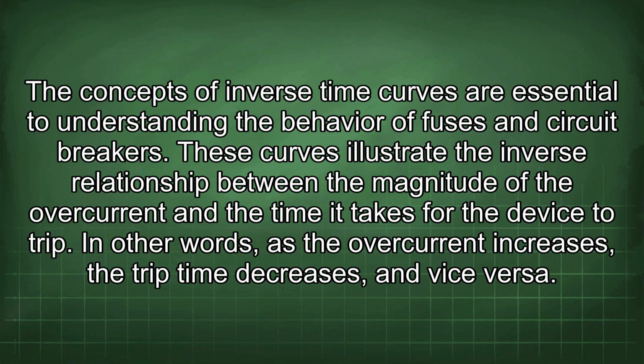The concepts of inverse time curves are essential to understanding the behavior of fuses and circuit breakers. These curves illustrate the inverse relationship between the magnitude of the overcurrent and the time it takes for the device to trip. In other words, as the overcurrent increases, the trip time decreases, and vice versa.